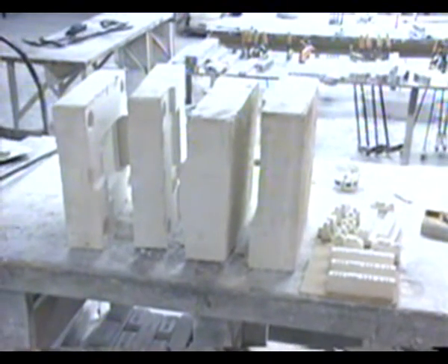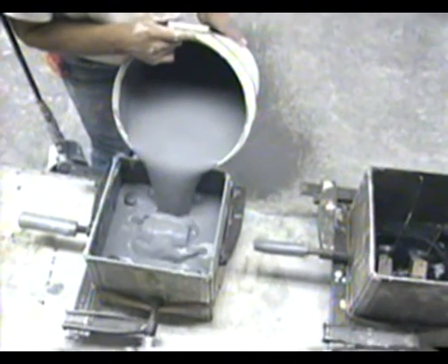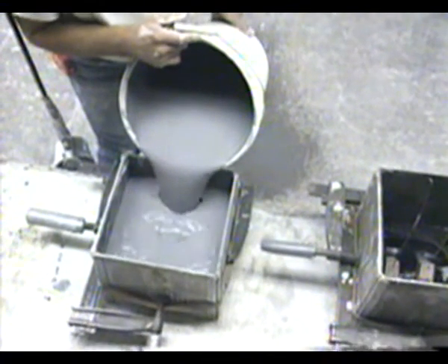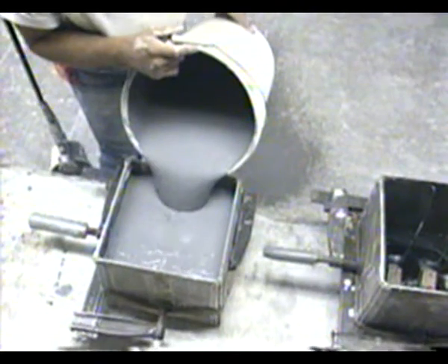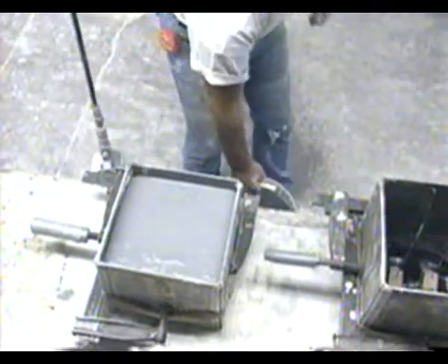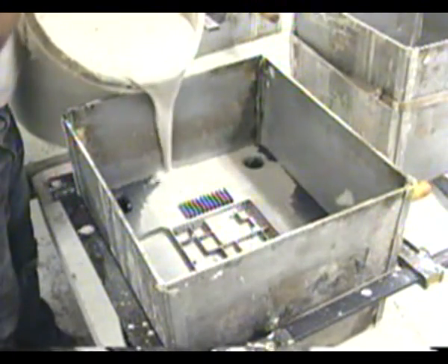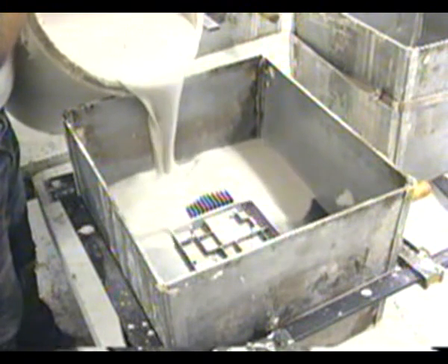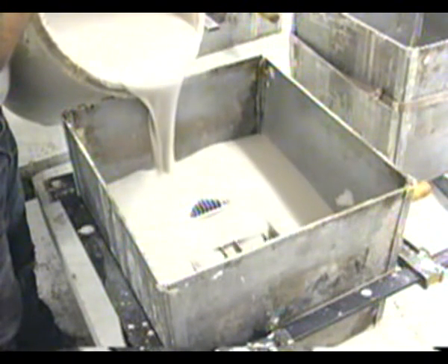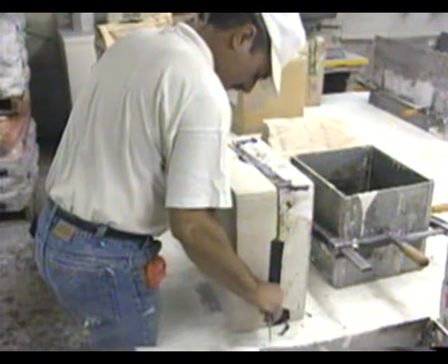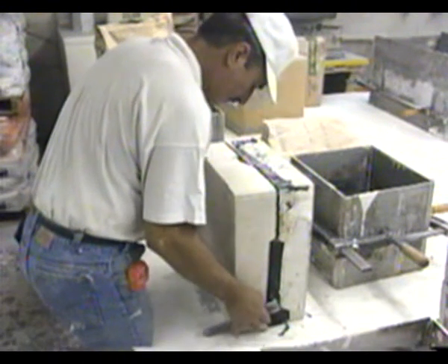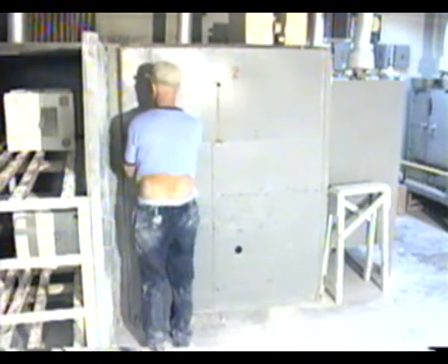Besides calcium sulfate, other mold ingredients may be used to improve moldability, reduce porosity, increase strength, and/or control contraction. The mixture, in slurry form, is poured over the pattern and allowed to set and harden. Once set, the mold is separated from the pattern and baked to remove the moisture.